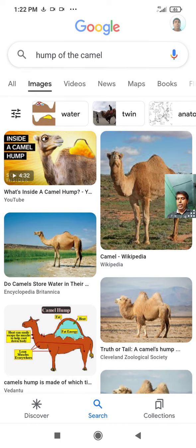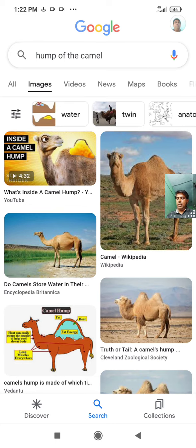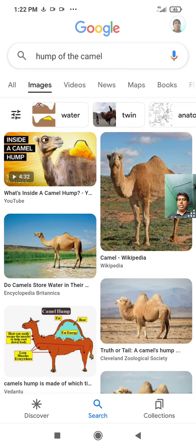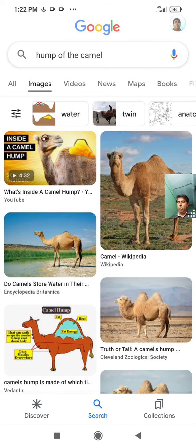Mislocated or poorly attached closures will subject the zipper teeth to very high stresses at the top. Garments that are sized small or retail customers that purchase undersized items promote failure because these closures are usually left open and the slider is used to keep the opening closed.